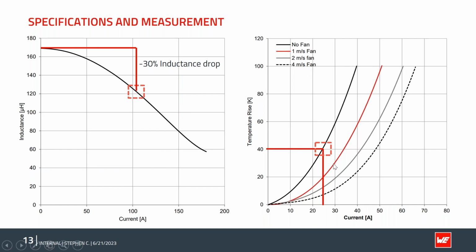And also, like I mentioned earlier, we did measurements of rated current under different cooling conditions. And we always recommend our customers select the part with the suitable rated current according to the cooling condition they plan to use. And this can help them avoid selecting a part which is overrated and resulting in a larger size or higher cost of the product.